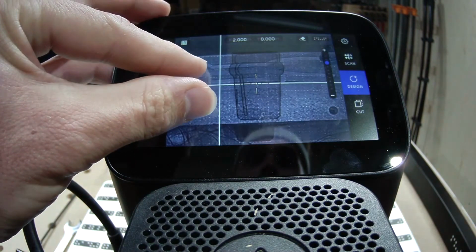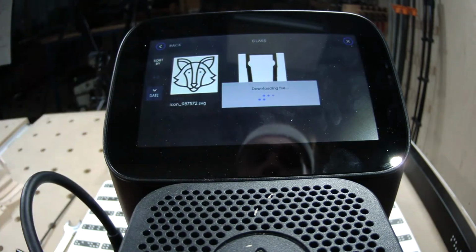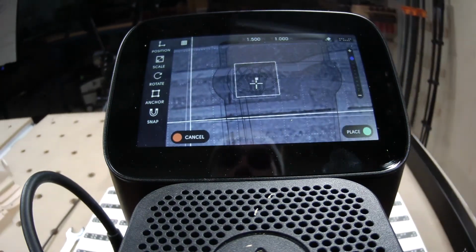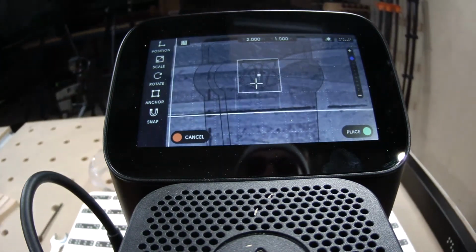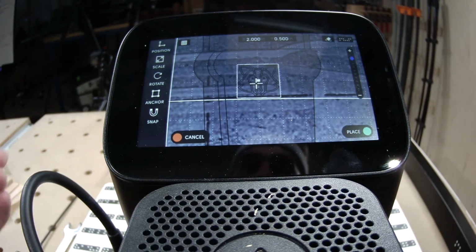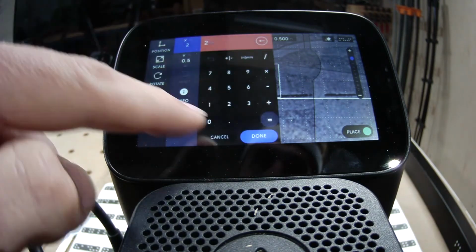And so now, what I want to do is add that logo into the glass. So I'm going to go ahead and import that icon. But what you'll notice is right now, because of the grid, it's snapping at 1/2 inch increments, and that's not giving me where I really want it, which is somewhere in the middle there. So what I can do is get it close to where I want it, go to position, and lock one of these axes. So I'm going to lock number 2.